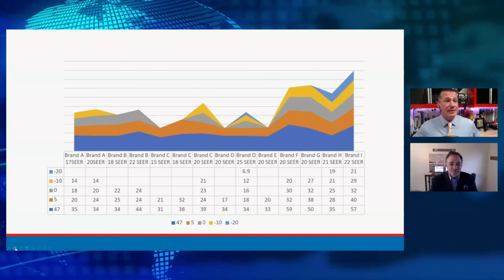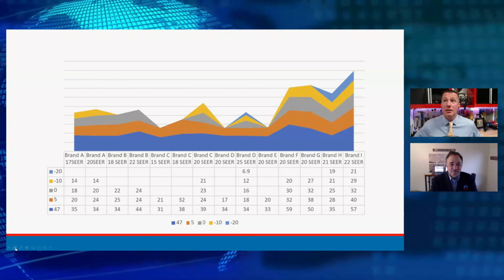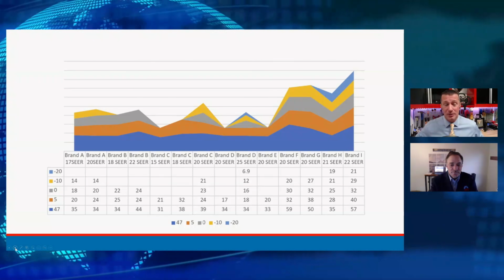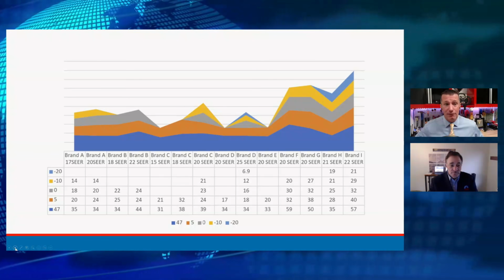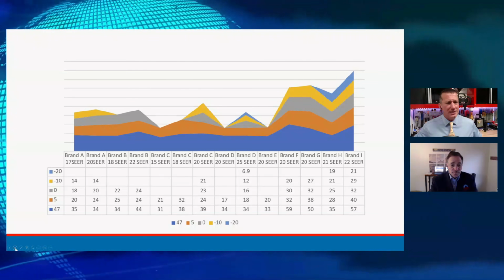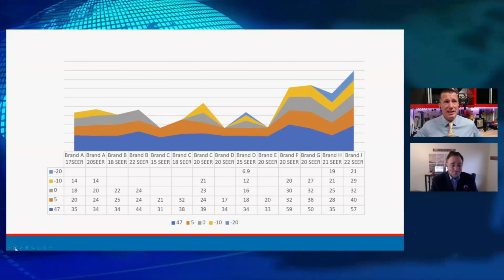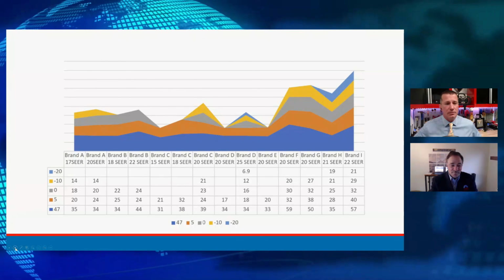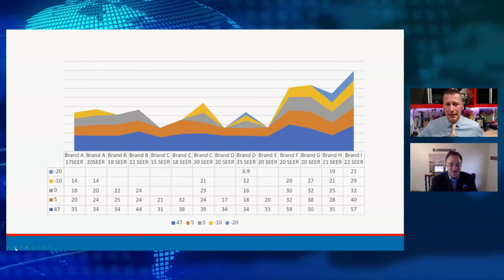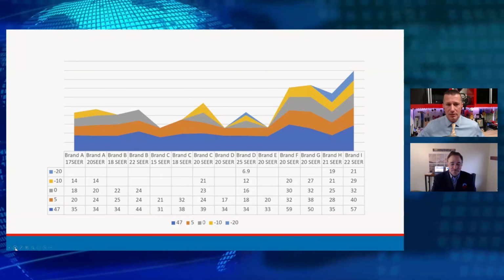Here's where things get hairy. Look at the BTU capability of that thing. That's that one that we looked at earlier on that NEEP chart. At 47 degrees Fahrenheit, that thing can produce 57,000 BTUs of heat. How do we do that? How is that a 3-ton heat pump?